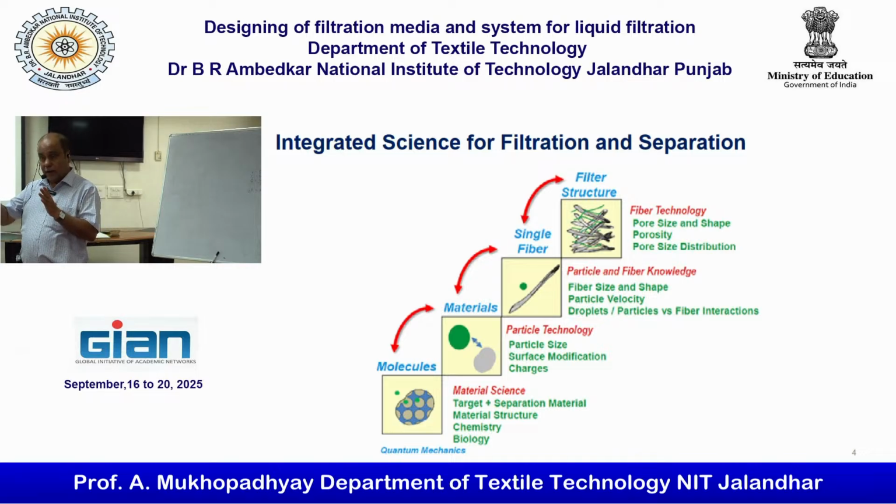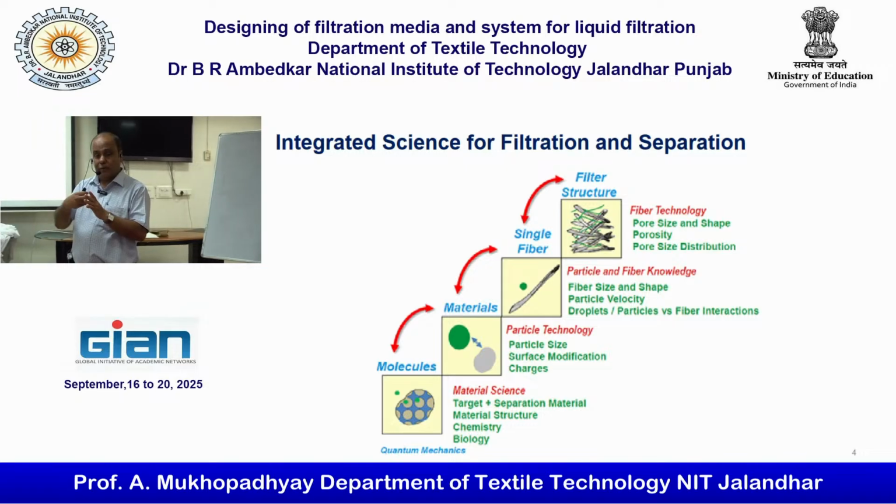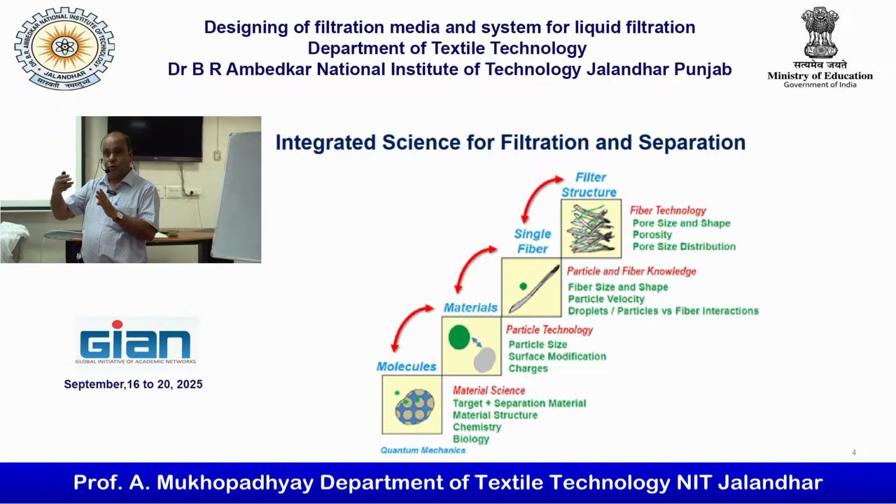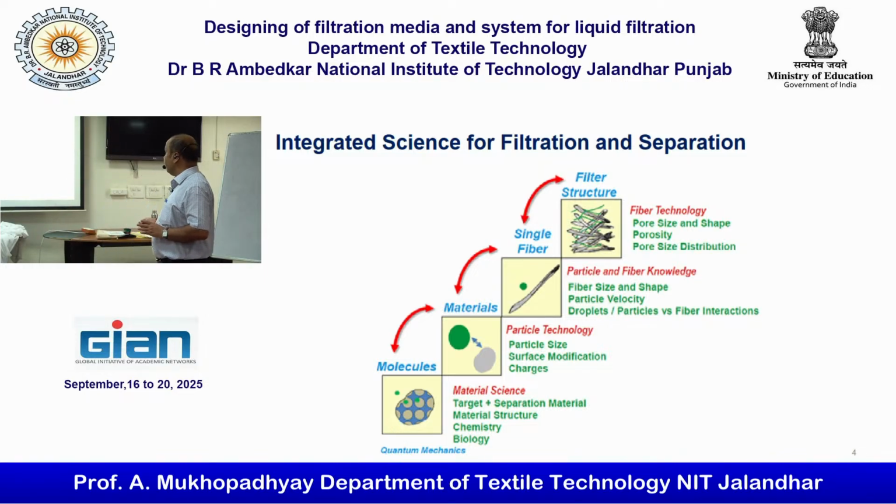There could be direct penetration or seepage whenever the liquid viscosity is more, so particles can penetrate through the media based on the size of the pores. Next is the filter structure, how we are making the medium. That also plays a vital role, because the media is an assembly of a large number of fibers. So the media role is important.